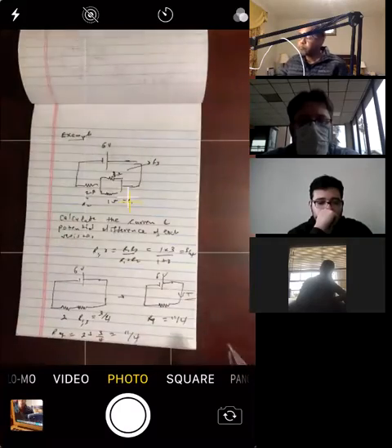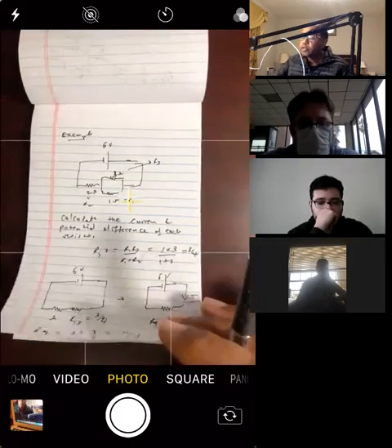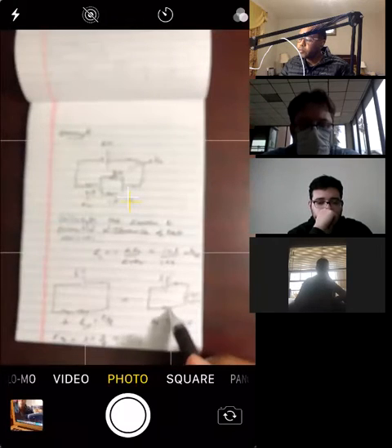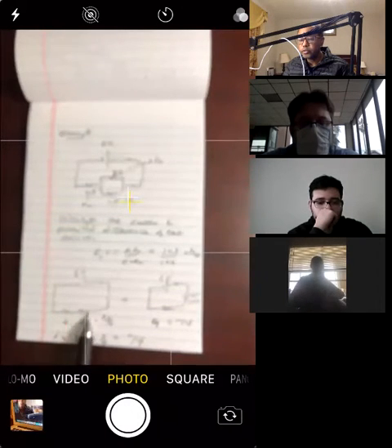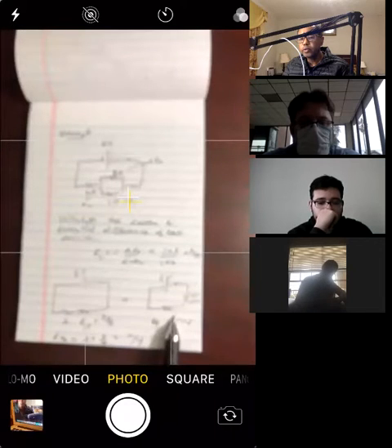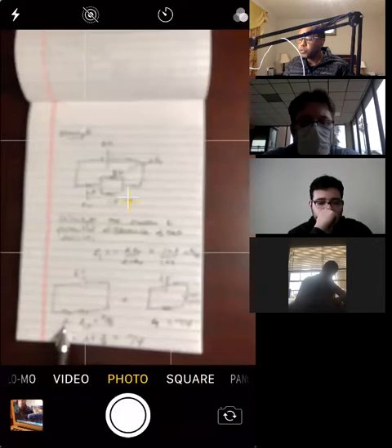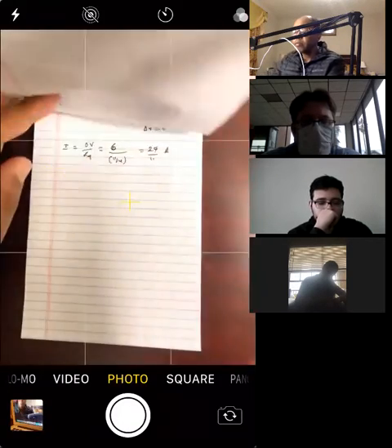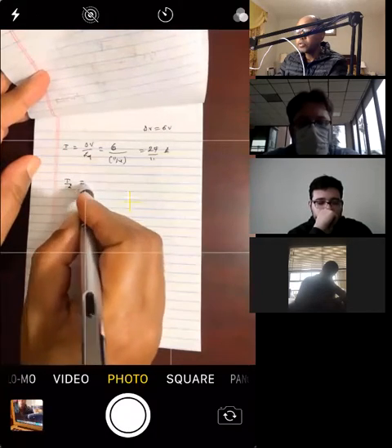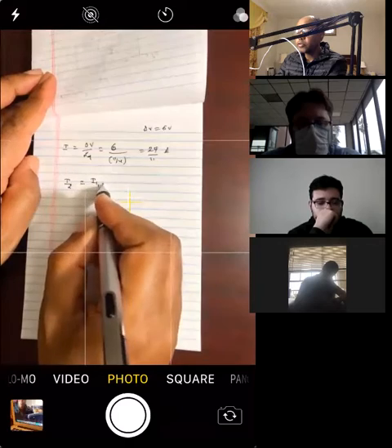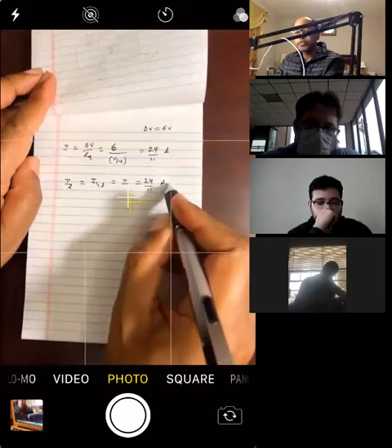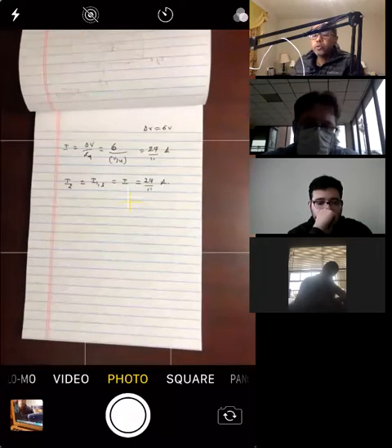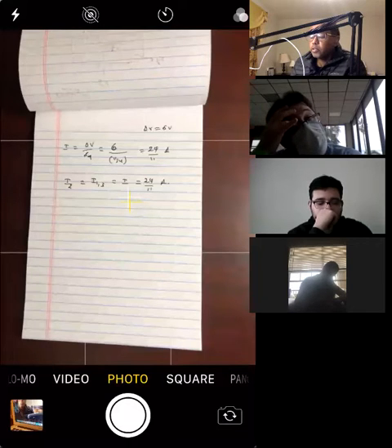Okay, now let's go back. The current over here is 24 over 11, right? What do you think is the current over here? The same thing. These two are connected in series, right? So you have the same current as this one, all right? So the current across 2 and the current across 1, 3 are the same, and they're equal to this one. So you can say that the current across the 2 ohm resistor, the current across the combination of 1 and 3 equals the total current equals 24 over 11 amps. Okay, moving backwards, all the currents are equal because they're connected in series.